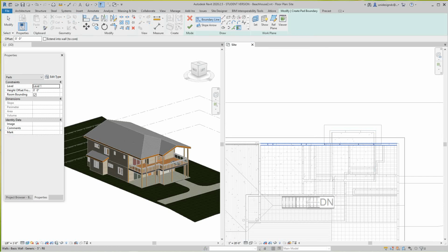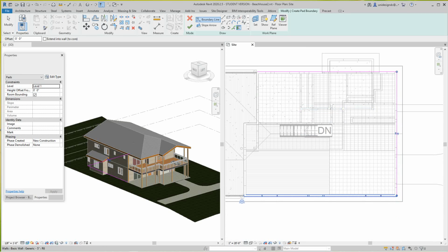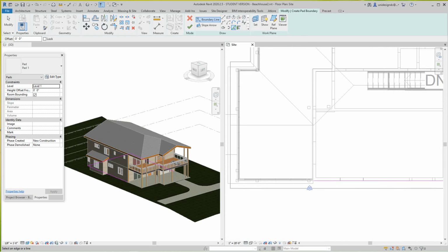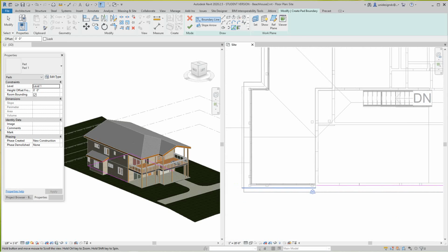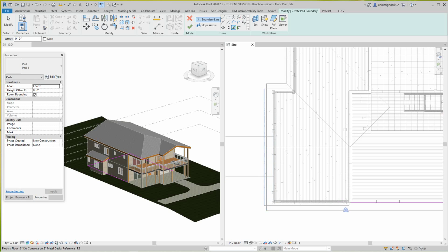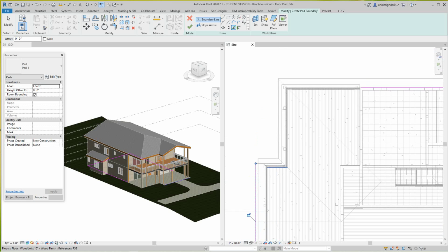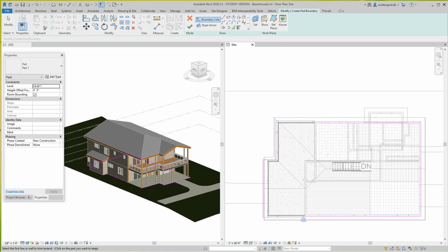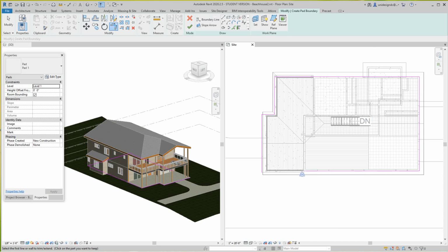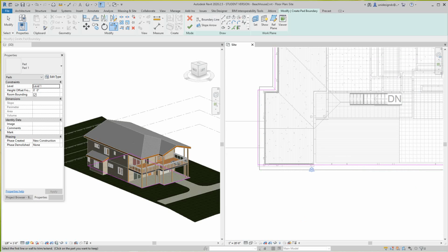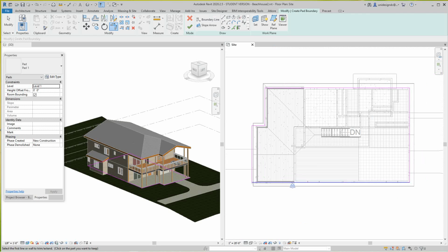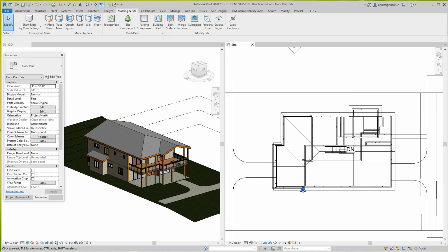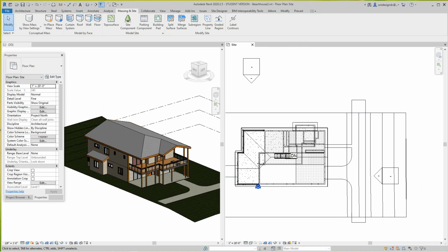So we'll select this wall, and this is going to come all the way out here. So I'll switch over to pick line, and I'll just pick this line, and then I'll extend these to intersect. This will be our building pad. Probably will need to be adjusted, and then we'll click finish. So we have our building pad underneath now. So then we can go back here and we can do a lot of things here.